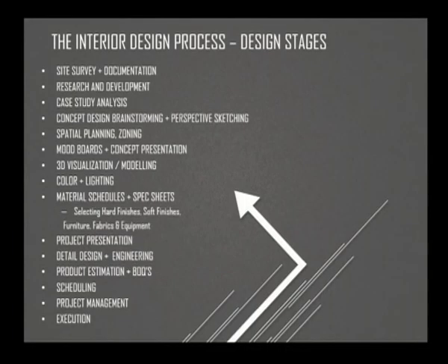So it's very important, first of all, to segregate the categories into private, semi-private and public. You also need to categorize zones into servant zones and served zones. See, servant zones basically talk about areas that contribute towards the served zones. So you're talking about a kitchen where something will be prepared, and the dining will be a served zone where the prepared item is going to be showcased in the dining area. So that's what a servant and served space is.